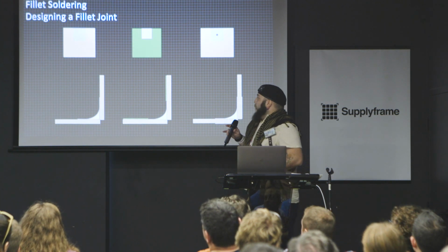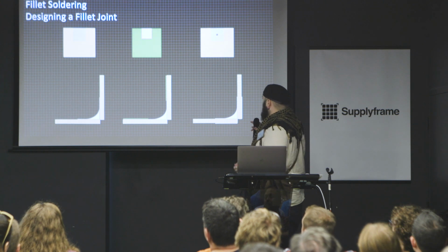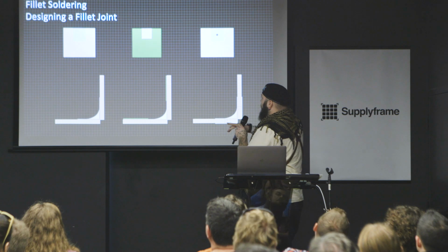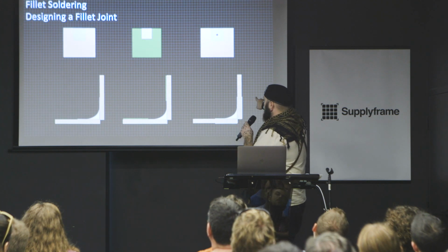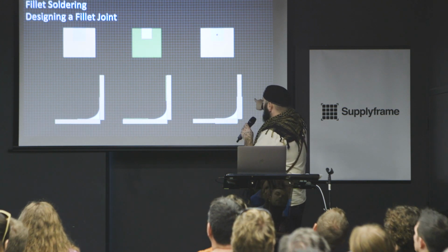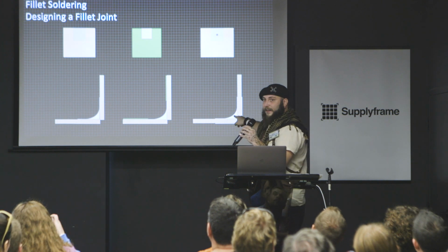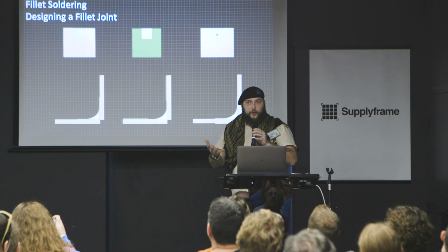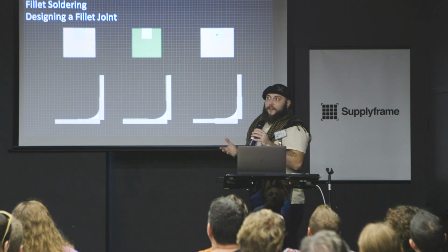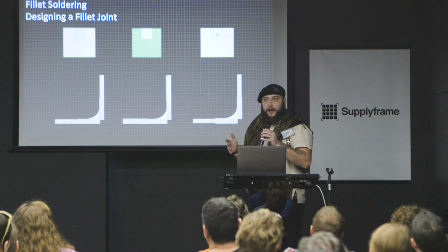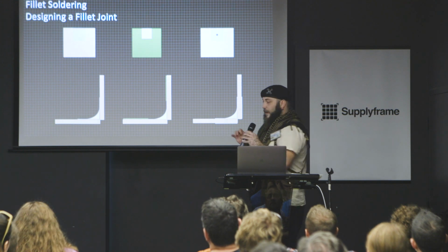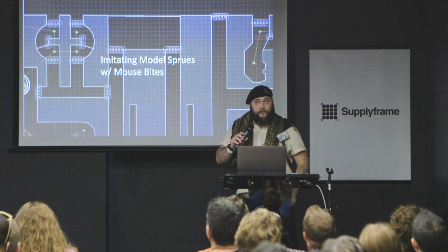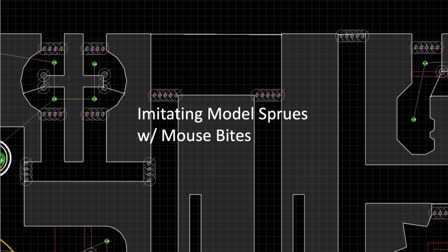So it turns out what you can do is go back to the simple method, and you can just do this galaxy brain method over here, where you drop a via in the middle of the pad, and that via basically acts like a rivet that goes through the board and holds it on the other side. So now you're not going to lift the pad when you heat it up, and it's actually kind of acting like a mechanical fastener. And it doesn't take very much real estate.